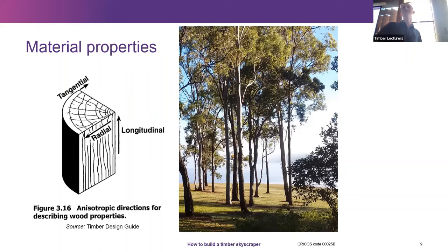The thing about timber that's really interesting, but also scares a lot of students, is that it is a natural material and it is not isotropic. It has 3 distinct directions, parallel to the grain. I should have brought a bundle of straws, but basically it's like drinking straws. Those are your timber fibers, they're hollow in the middle. So that's what we call the grain direction.